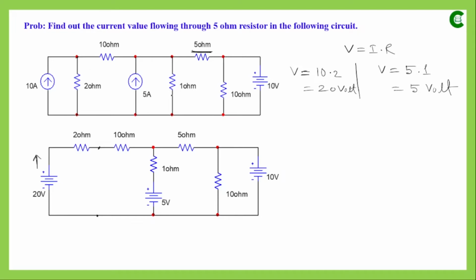So this has already been transformed into a voltage source. Instead, these two, the current source and this resistance, were connected between these 2 points. So finally, after transformation, when we connect the voltage source and this resistance in series with that voltage source, they will come between these 2 points only, and this is the connection in the modified circuit.